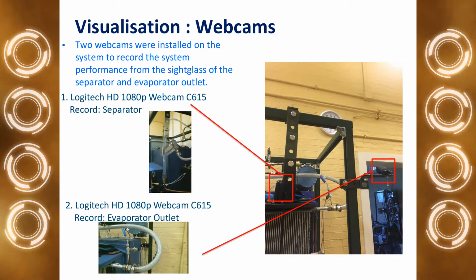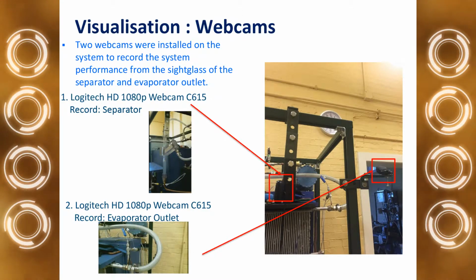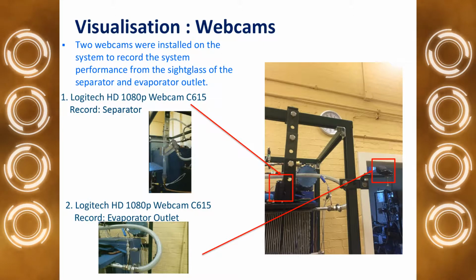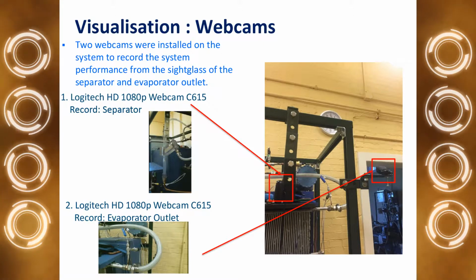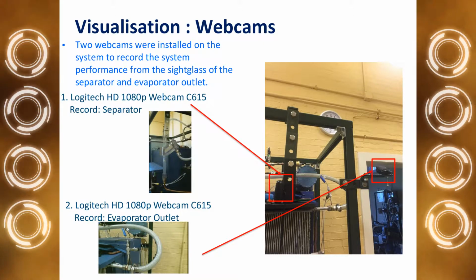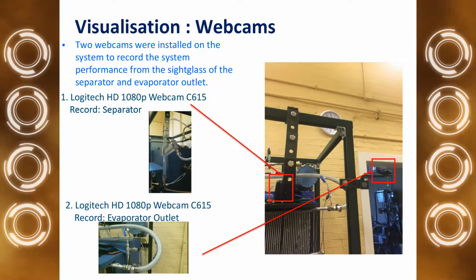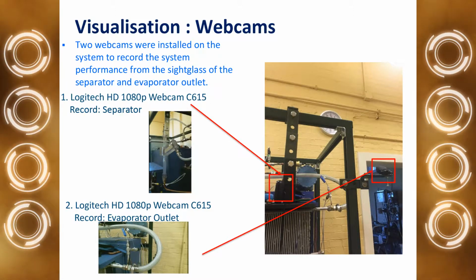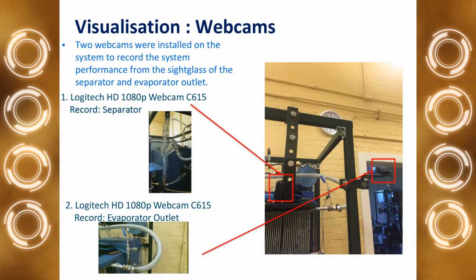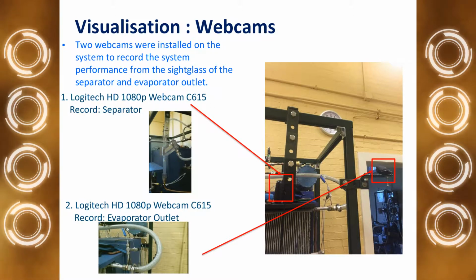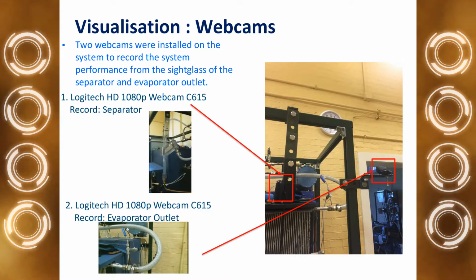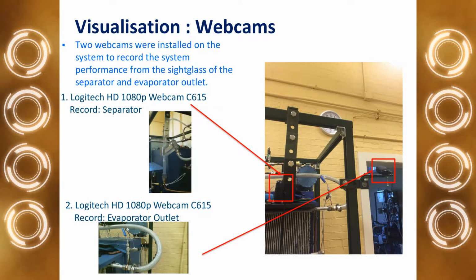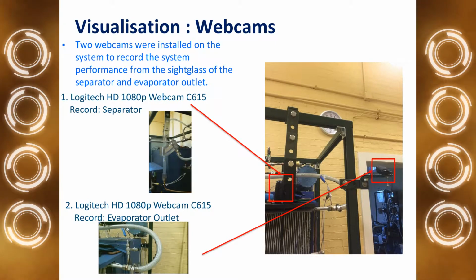So we are actually leaving a little bit of, maybe you can see, maybe not, some of the liquid going out from the evaporator. Here is the evaporator outlet, and some of the liquid is coming out from the evaporator because we don't want to have any superheat in our microchannel heat exchanger. And then that liquid goes to the internal heat exchanger, and after that goes to the compressor suction.